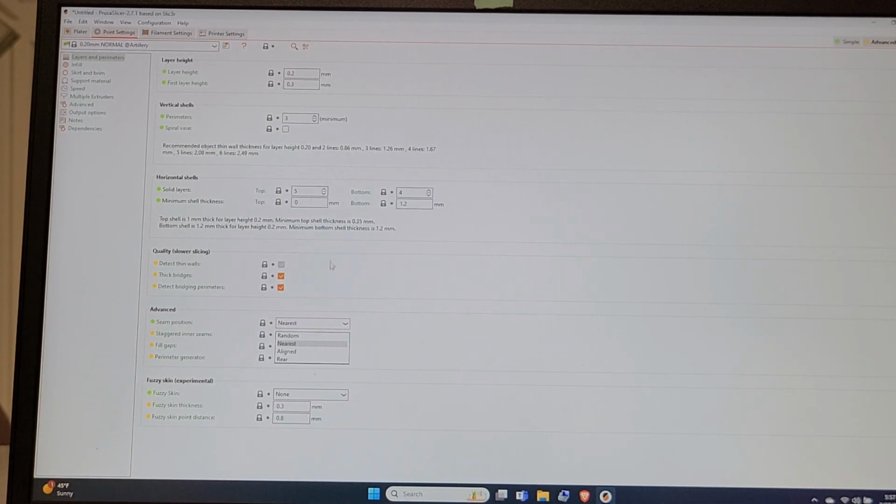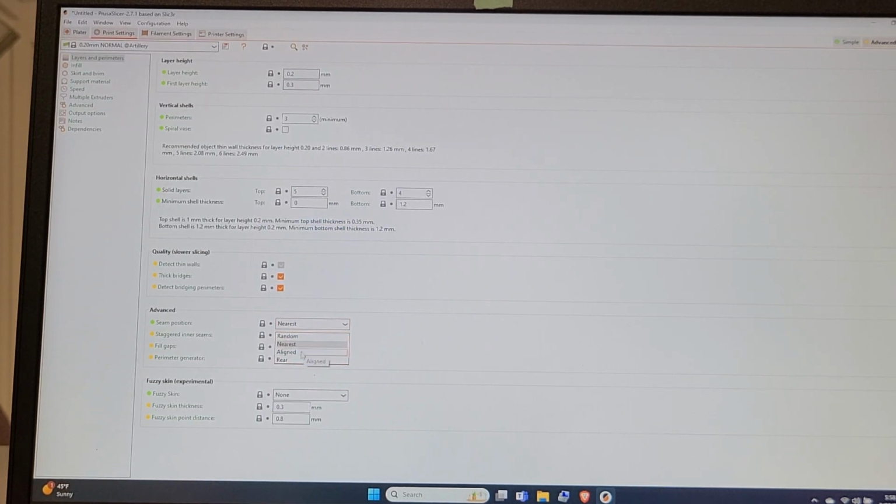People will notice that if they have issues with the retraction settings and they notice little pock marks randomly around their prints. That's the Z seam set to random. You can tweak that later on. I'll tell you how to tweak things to minimize the Z seam or even try to hide it. But for now you can just choose what position you want it in, and like on Cura you can choose the sharpest corner. I'm sure that's what aligned is.